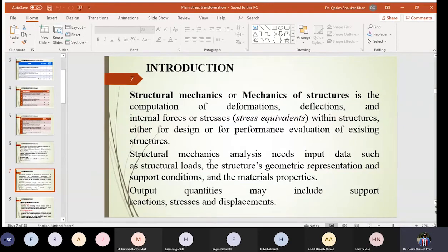That's why you see more rectangular columns and fewer circular columns. The reason is the formwork and the labor cost. However, the best geometry is circular because it gives uniform stress distribution.